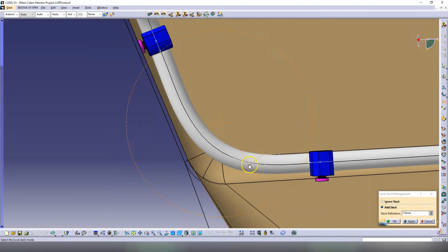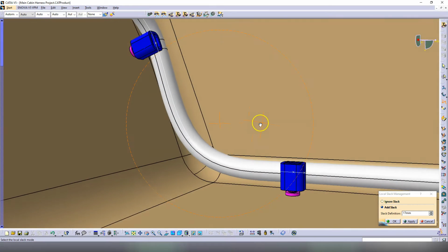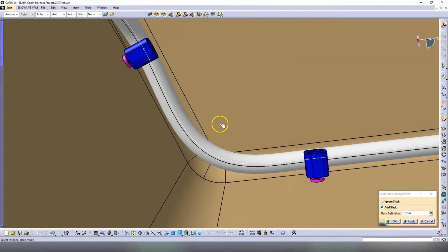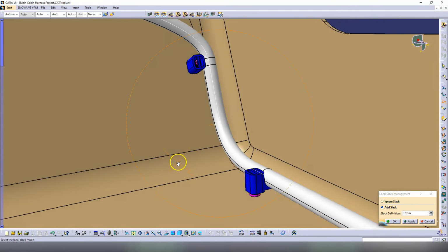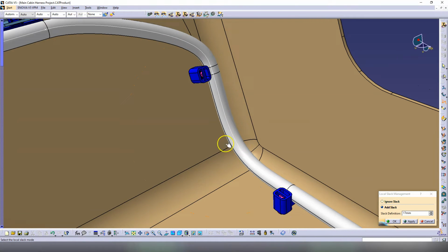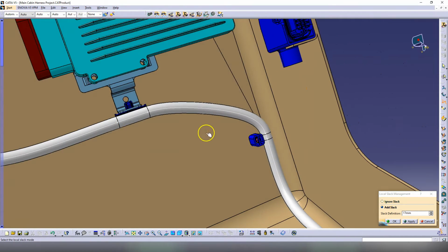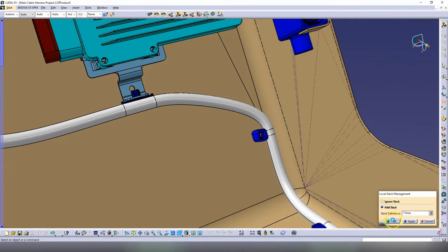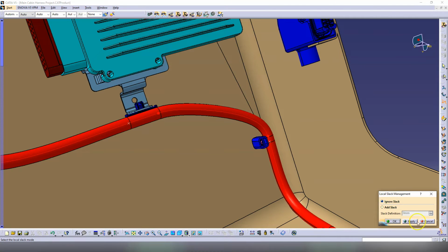body in white. And depending on how thick a piece of harness is, the more rigid it is going to be. So that's important, because when you add a lot of slack, then you need to make sure that it's not too flexible, and if it's a smaller harness it's going to vibrate on the body in white, because that's very bad when they do the testing for the vehicle and you hear a rattle noise, a piece of harness rattling on the body in white inside the vehicle. That's very bad for the quality department.